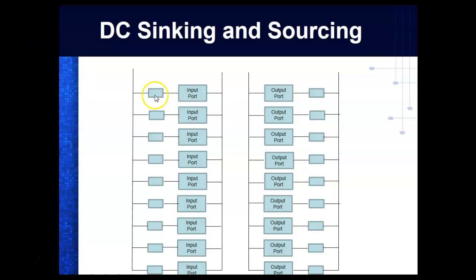So our PLCs are wired, it's running sinking inputs. That means our PLC, this is going to be a plus. So that means the PLC is a minus on this side, which you can't see. And it's running sourcing outputs. So that means this is a plus on the output port, and this right here has to be a minus.